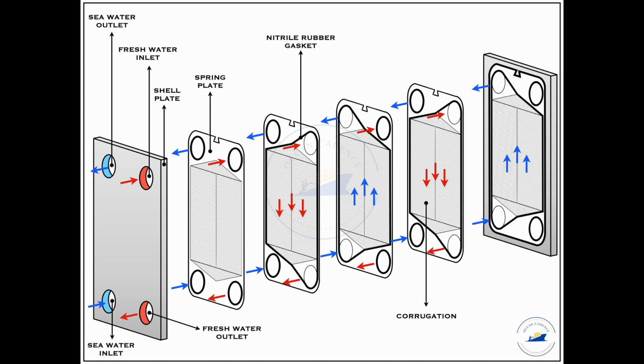This will also mean that the heat exchanger fouling will be much higher as compared to what we observe in the alternate arrangement. So what we do is that if the cooling medium is entering at one point, then the simultaneous arrangement for the fluid that is about to lose heat will always be the exit point, and similarly at the exit point of the cooling medium, the inlet of the heat loss medium will be arranged. So it has been found that by doing so, the thermal stresses are not very high in the cooler. The gasket will obviously run for a longer period of time due to lesser expansion, due to lower temperature gradient occurring, and also less fouling of the cooler will occur.